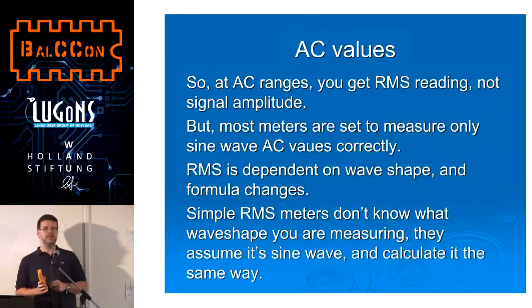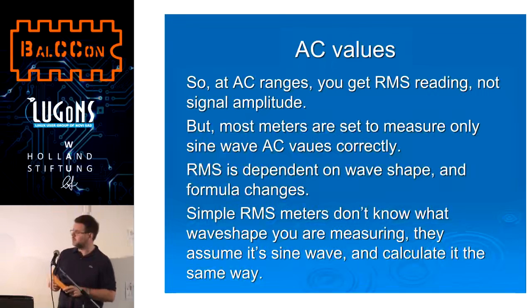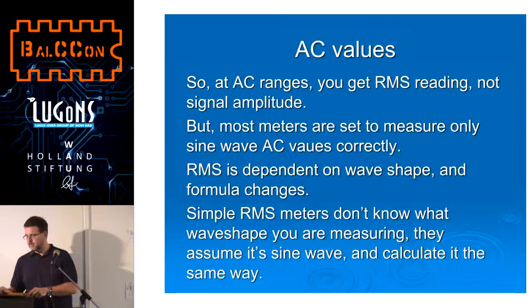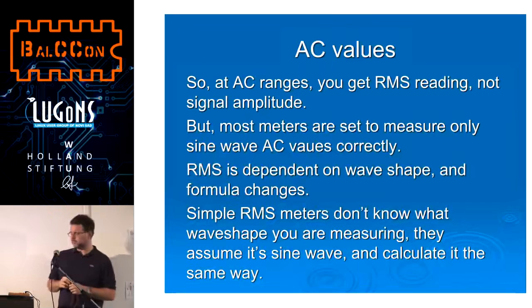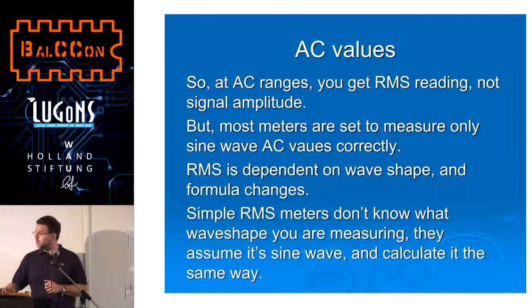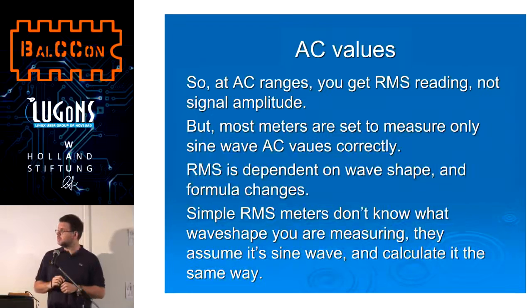Any other wave shape will get some error when measured, because your multimeter doesn't know the wave shape of the measured voltage. For that you need an oscilloscope.